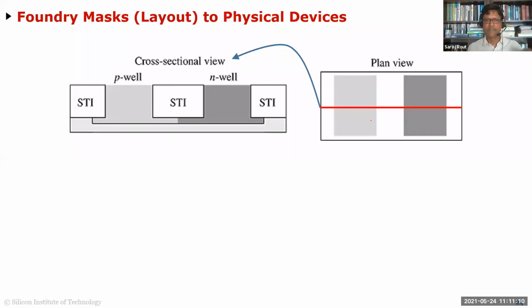This is not what's called a monolithic process. You don't pick devices one by one. You don't pick the NMOS first and fabricate it. You don't pick the PMOS. You actually develop all portions of every device at once. In the sense, all the N wells of all devices will be done at once. All the P wells of the devices at once. All the gates of all the devices will be done, because these are planar. Once you're done with that layer, that's it. You go to the next layer and so on.